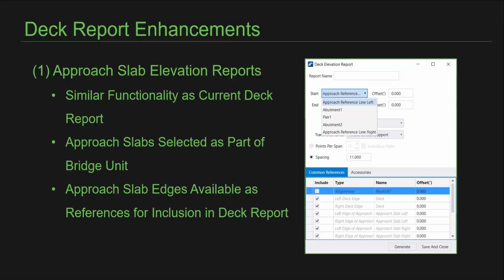In this video, we will review the enhancements with the deck report in the latest release of OpenBridge Modeler. The first enhancement is the new capability to include approach slabs in the deck elevation report. Maintaining the same functionality as the current deck report, approach slabs can now be selected as part of the bridge